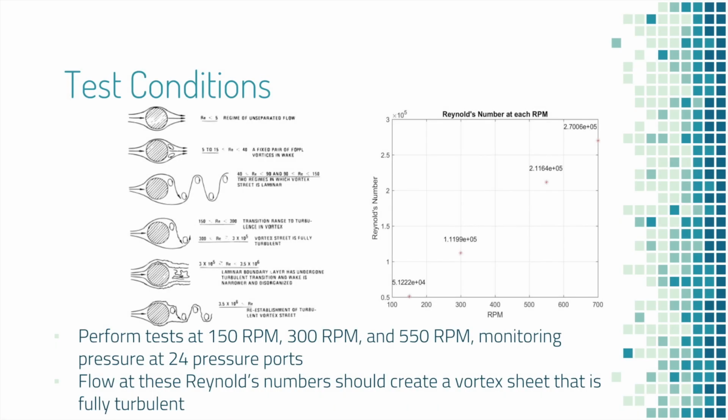In terms of test conditions, these tests were run at relatively low Reynolds numbers, typically between the orders of 10^4 and 10^6. This range follows the flow regime such that a cylinder is expected to shed vortices and form a von Karman vortex pattern. The wind tunnel speeds were controlled by setting the wind tunnel drive system to spin at a fixed RPM with the variable frequency drive, or VFD.